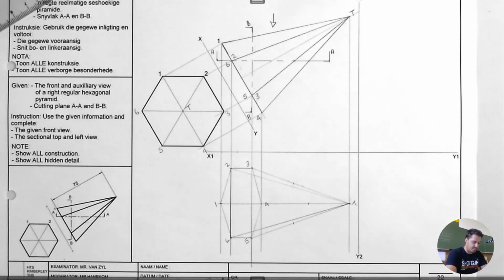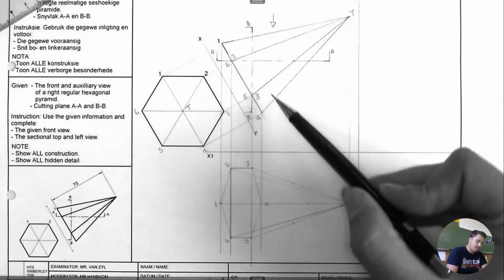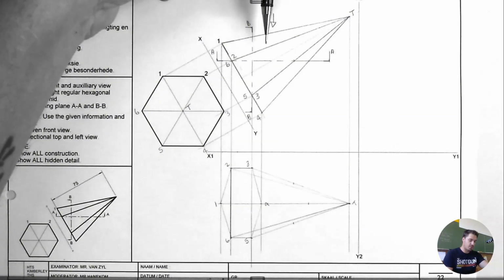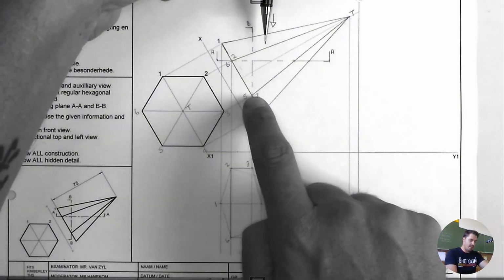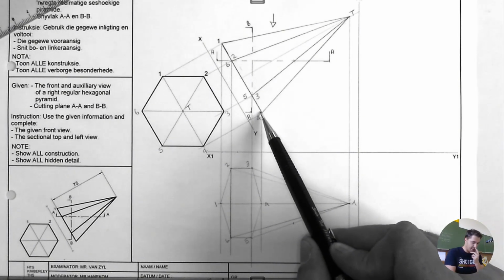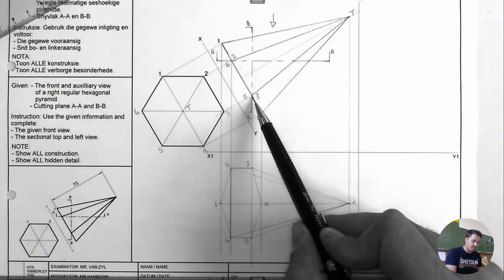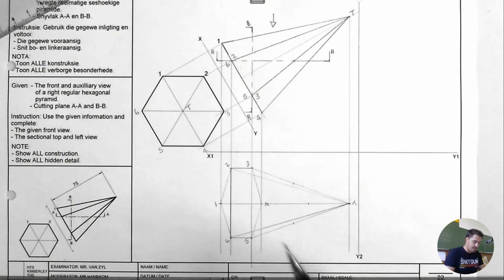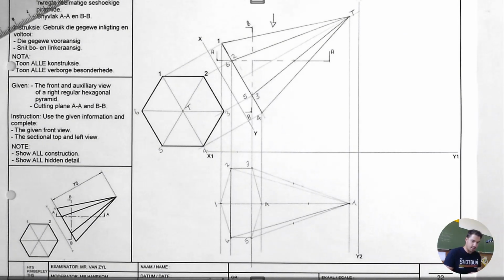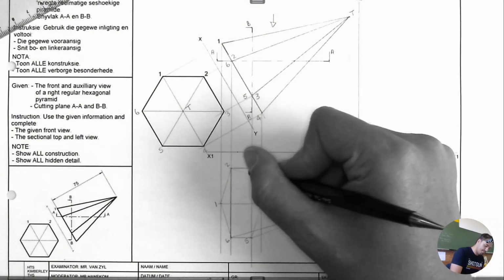Alright, now, before we even draw in the cutting plane, let's see what's visible and what isn't. At the very bottom of the drawing, remember you are looking at it from the top like this. So you won't see point 4 as it goes to the top. That's hidden detail. 5 and 3, so on the base forms the shape of the drawing. So 4 goes to 3, 4 goes to 5. That will also be hidden detail. So as it stands, 4 going to top, 3 to 4, 4 to 5. That's hidden detail. So if you have to draw it in,